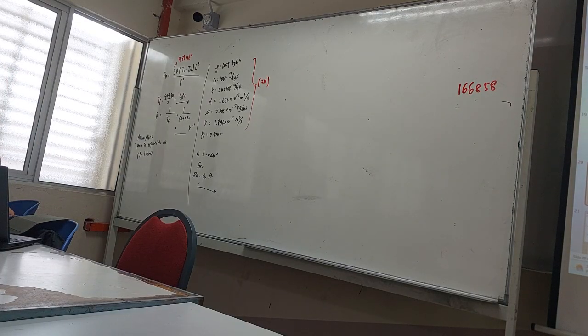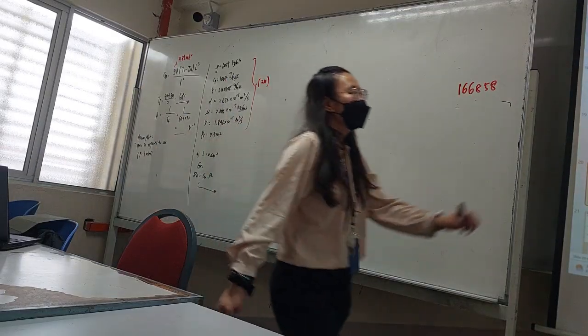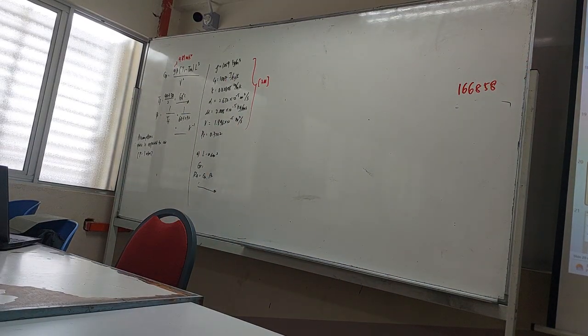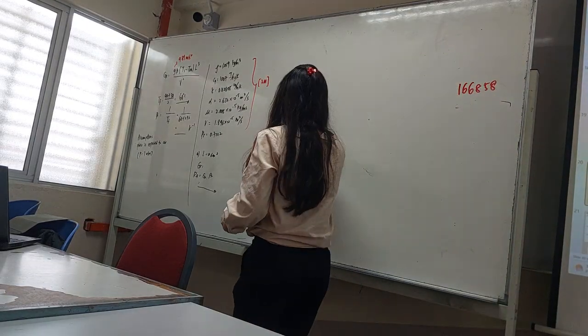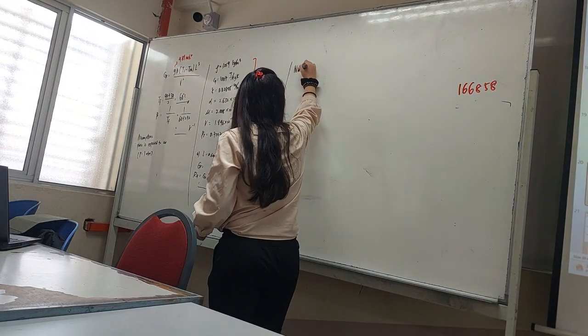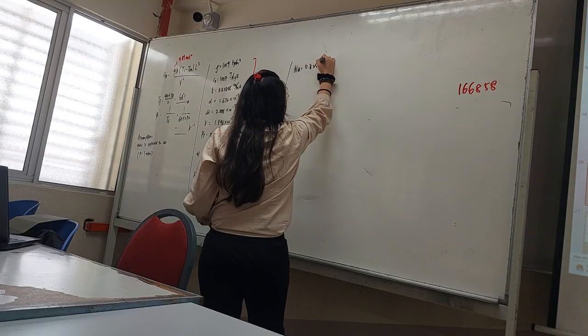For the vertical plate, we are going to use the entire range. Normally, if you have a vertical plate, we will use this one because this is the accurate one. If you use the first and second, normally it's not accurate. So the third one is the accurate one. So normally I will use the third one to do the calculations. Okay, so then you substitute into the equation. Nusselt number equals 0.825 plus